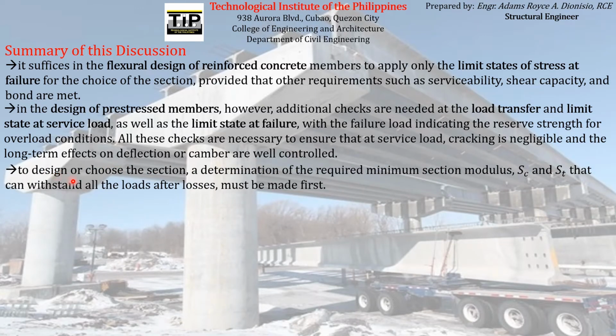So to design or choose the section, a determination of the required minimum section modulus (SC and ST) that can withstand all the loads after losses must be made first. So in order for us to solve for those minimum section modulus, we can use two scenarios.